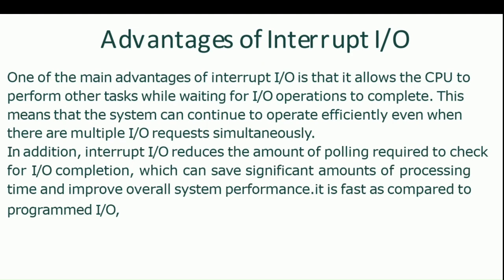Rather than continuous checking for data availability, the programmer can set up interrupt handlers to handle specific events or interrupts generated by input output devices. Next advantage is scalability. Interrupt driven input output is more scalable in systems with multiple input output devices. Each device can have its own interrupt signal, allowing the CPU to efficiently handle input output operations.